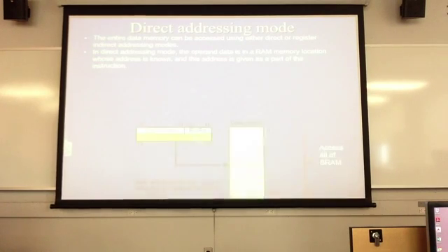All right. So the direct addressing: LDS, Rd, and then you just give it the address. We went through this the other day. Here's my opcode. Same thing over here: my opcodes are set up here, then we have data, and then we have the physical 16-bit address that goes here. So 0313 would go right in here.